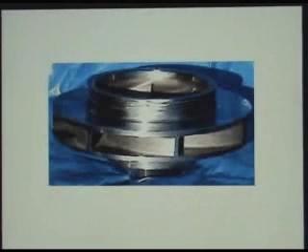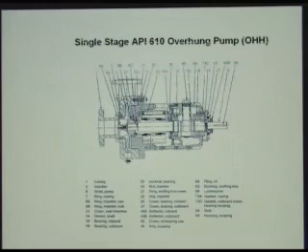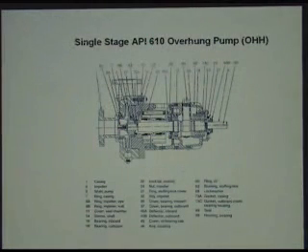That's what one of the impellers is going to look like. Not necessarily big. These are generally cast with not a lot of machining done on them, a little bit on the outside diameter to get them to whatever size and final shape you're after. So this is a fairly typical sectional view of a single stage overhung pump. We have an end suction, a top discharge, and that's probably 90% of the pumps that you guys are going to see, because that's 90% of the ones we buy.